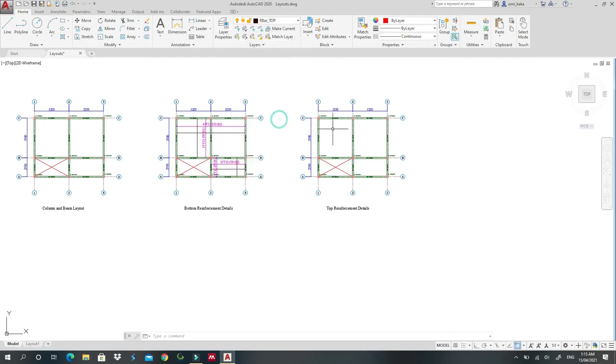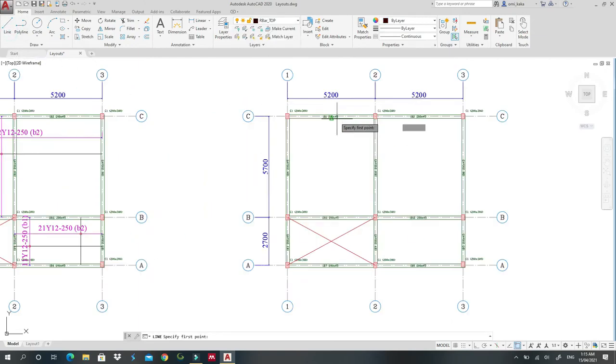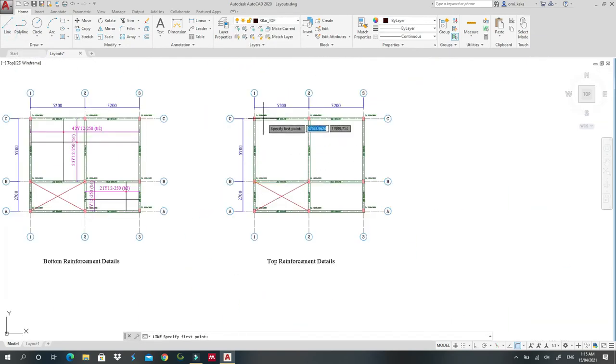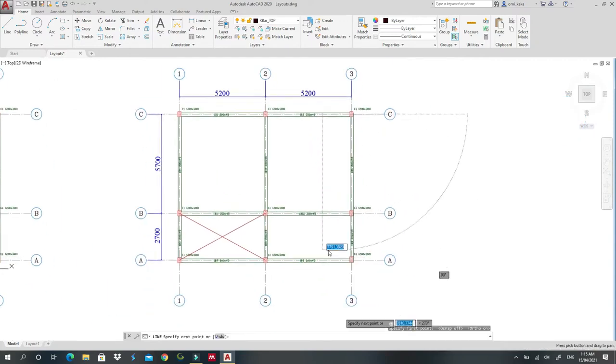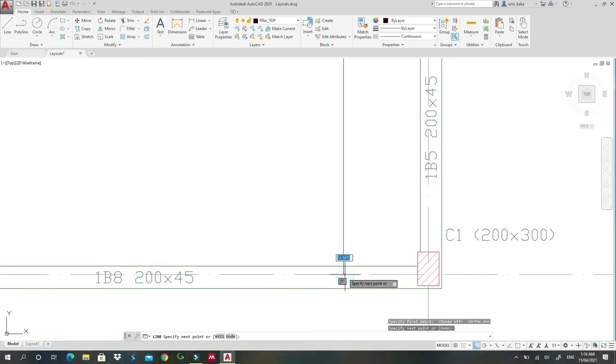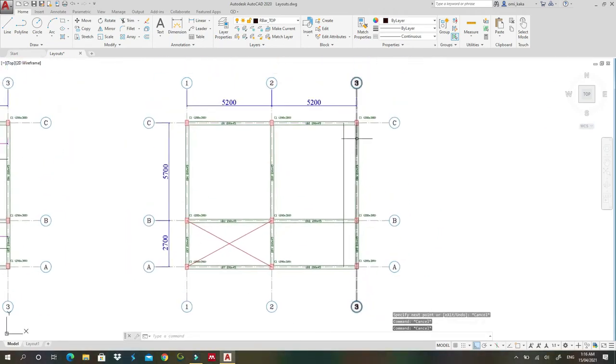and let's say rebar top, and then what I'm going to do, first of all, there will be a reinforcement. I'll start from here. There will be a reinforcement from here till down here, and this reinforcement will be arranged for the distance of 5200 divided by 3, so until somewhere here. So he'll arrange the first one, the second one, the third one, until he gets to 1/3 of this panel, and then after that you should